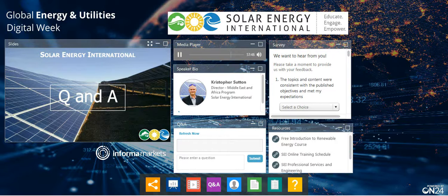That's why if we live in a place where we have a utility grid that comes on and off a lot, and I want to grid synchronize, then I'm going to need a battery to have a backup system if I want backup. But a normal grid synchronizing inverter shuts off the second the utility goes offline. The feature is called anti-islanding.